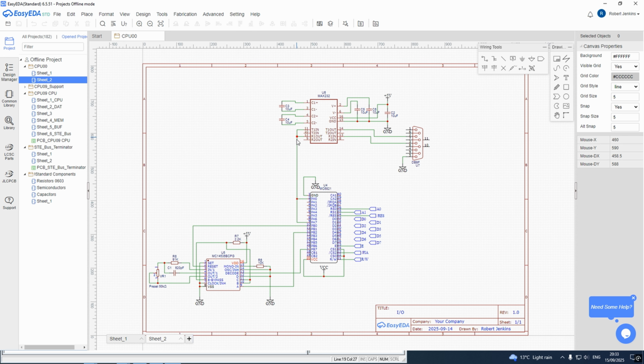There's only a single communications wire, which means with this being a push-pull output, it's got to be overridden by the PIA output to actually send anything. It really needs a diode and a pull-up resistor to give it a kind of OR function to convert this receiver output into just a pull-up, so it can be overridden and pulled down. So either that or the other IC can pull it down, but nothing can force it higher other than the resistor, which should work better.